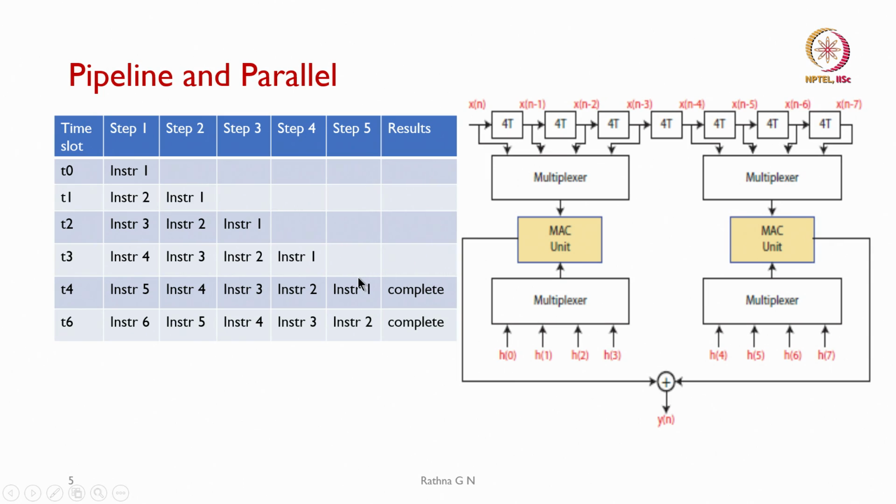Execution can take from one clock cycle to multiple clock cycles, depending on the hardware we are going to use. So, in most DSP processors, our add is going to be in one clock cycle, I can complete my execution, whereas my multiply MPY operation is going to take 2 clock cycles, whereas with the load and store architecture we said it is going to take 4 clock cycles, and